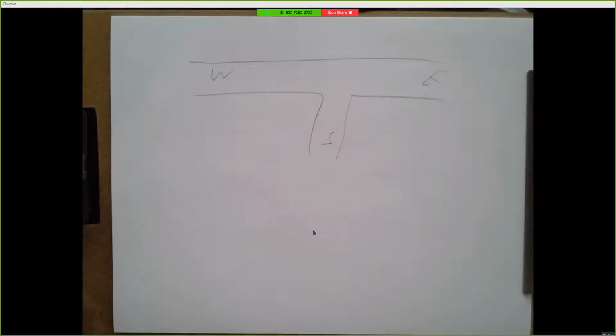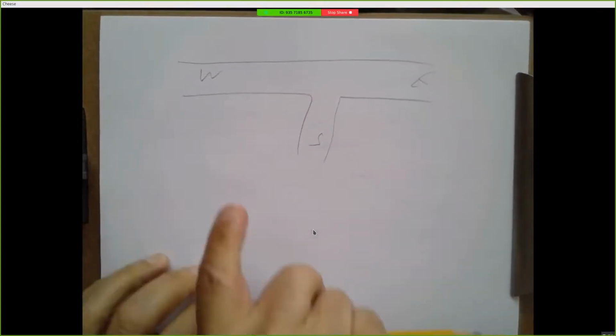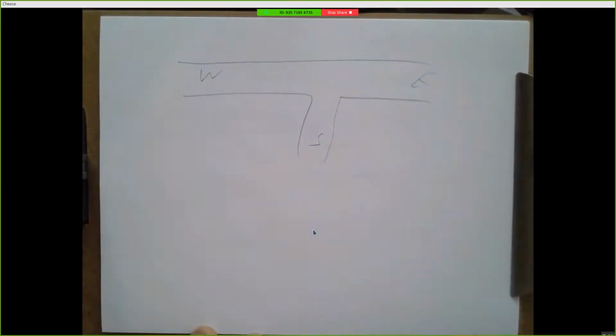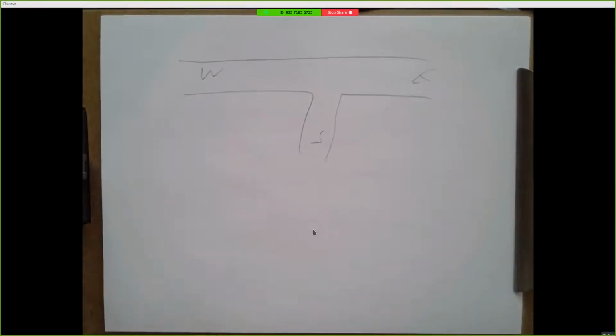Here's a way to think about this in terms of states. At any given moment, there's a lane that has priority, right? Assuming you don't have a state where all the lights are red, because that's just kind of mean. So go back to lab 3 where we had just green and red lights. One of these would be green, the other 2 would be red. Okay, so that system had 3 states. When we put yellow lights in, we've really only got 6 possible states.